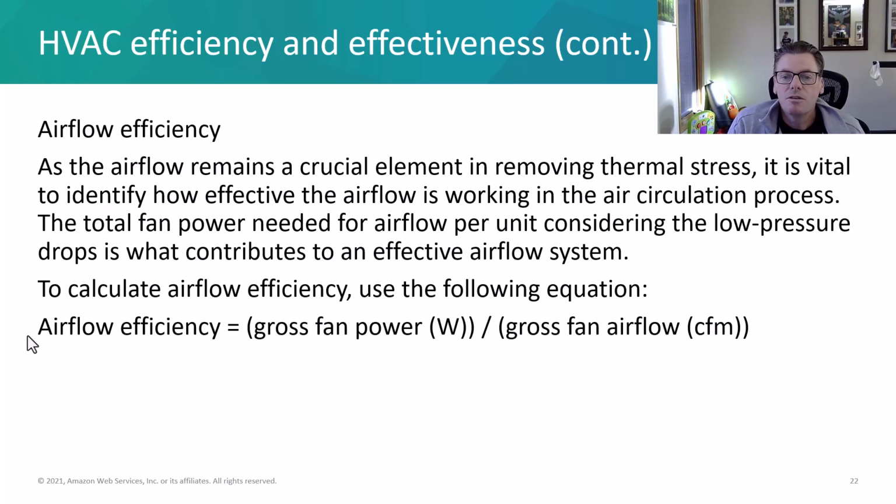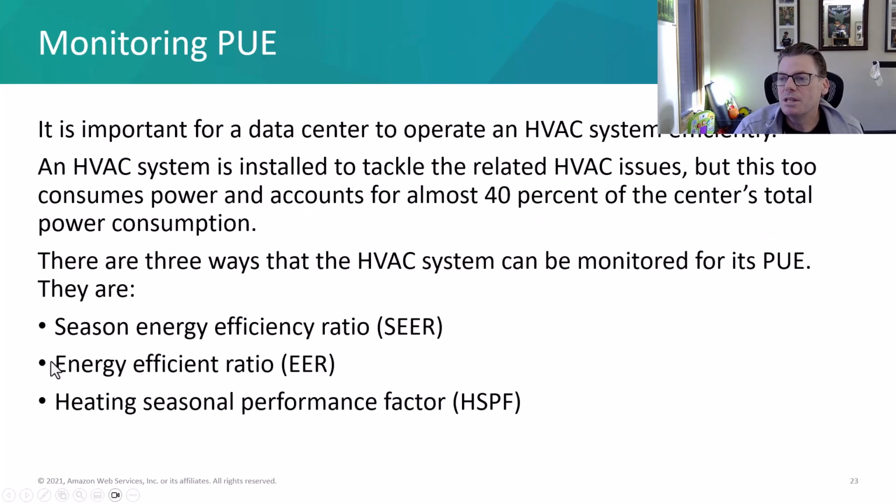All right, so our airflow efficiency is going to remove, it says here, remove thermal stress. Yes, it's going to take heat from inside and put it outside and bring cooler air inside. So to calculate that, we're going to look at how much power, how many watts do we use for our fans versus how many cubic feet per minute of air can we push through. Right? How much energy does it take to move a specific amount of air? And that's what we're looking at for our airflow efficiency measurement.